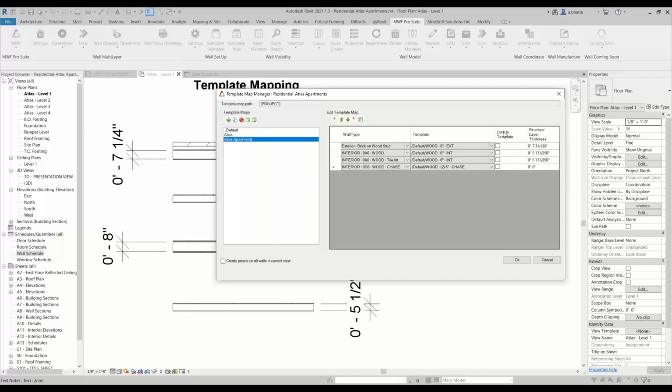All right. Now I have the option to lock all of these panels to the templates, and you can definitely lock them. If you lock the panels to the template, it's similar to multi-layer when you go to properties and it's locked to that template. What it will do is it won't let you modify that wall unless you unlock that wall first and then apply the templates or fix up the template however you would like, right? So what I'm going to do is lock the exterior with template, but the rest of them I'm going to leave unlocked, okay?